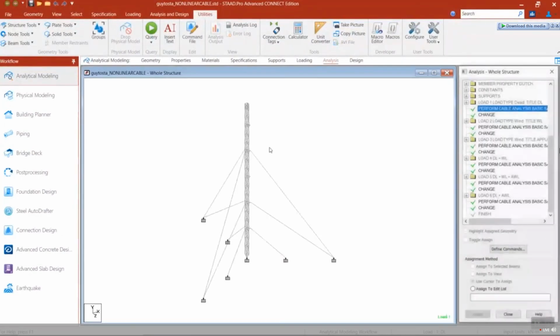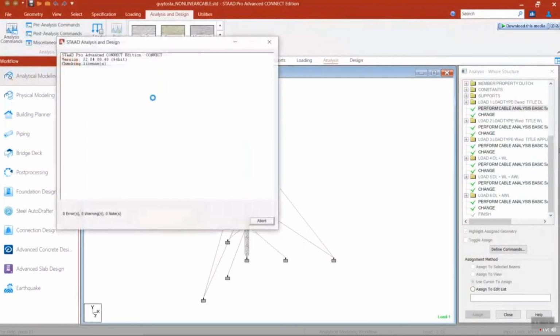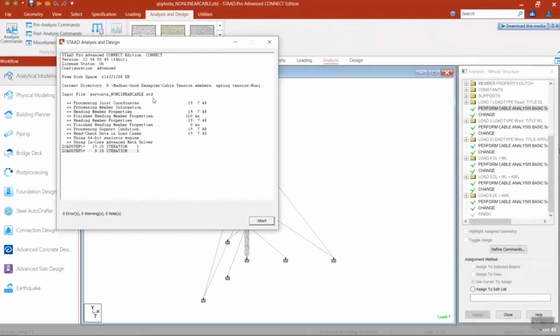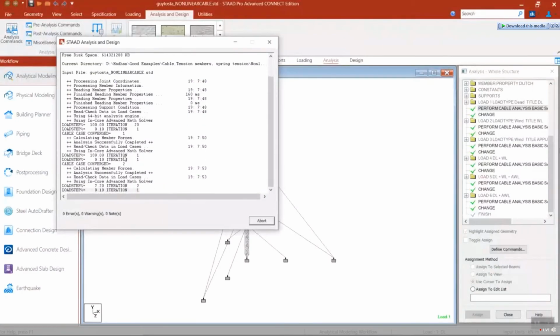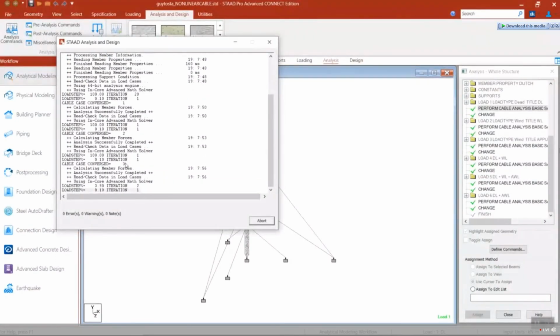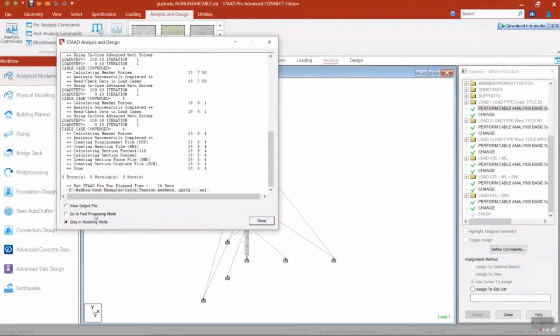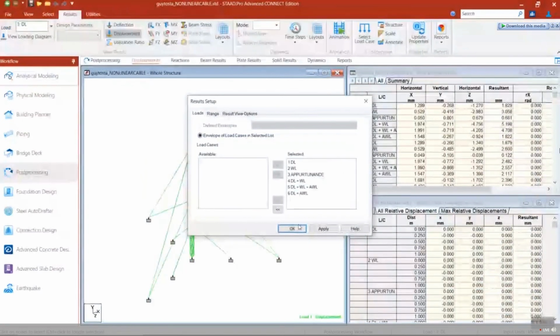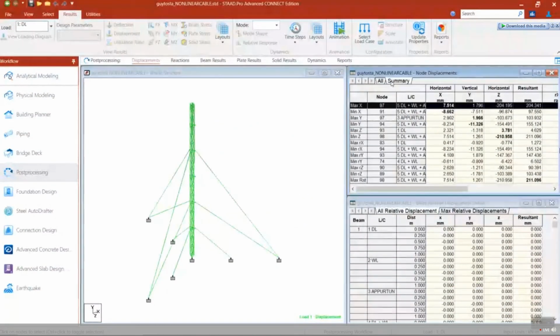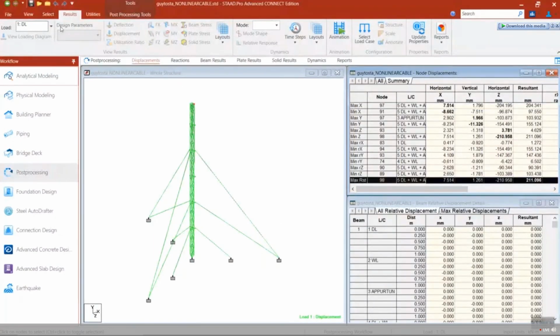And the initial tension, I leave it at 1, because sometimes you may not achieve higher initial tension on the cable on the site. So I leave the initial tension as 1 and I start using the sag minimum parameter and stability parameter. And now I can see the cable case converges. So with this example, I explained that there are multiple solutions possible, either by increasing the initial tension on the cable or by playing with the sag minimum and stability parameter in the model.